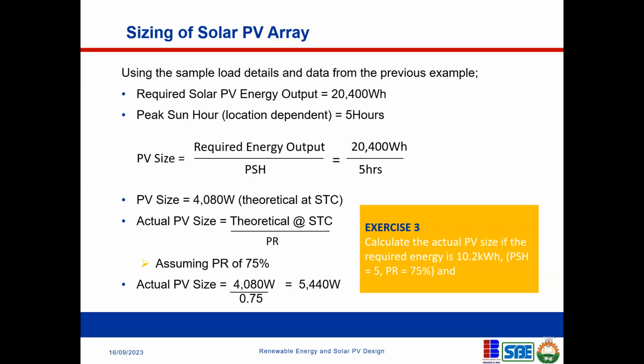Okay, I said you just talked about the fact that our batteries were 50% depth of discharge. So we actually don't need to generate this whole energy to feed our battery, given that we'll only be charging 50% of the battery. Okay. And even in addition to this, when we decided this 20,400 watt hours, it was for 3 days with 2 additional autonomous days, right? That's correct. And then the peak sun hour of 5 hours is a daily peak sun hour.